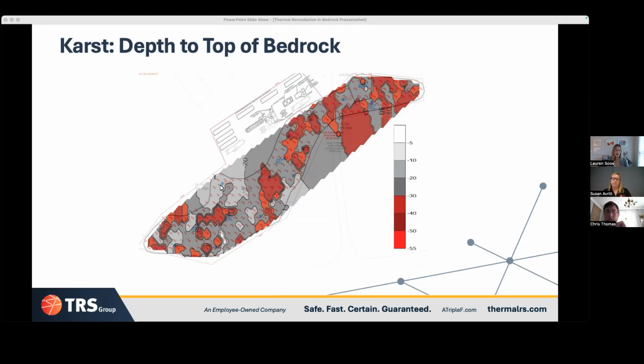And we are monitoring throughout the entire depth interval of the treatment. At this particular site, I believe we use, Chris, was it every 5 feet or 3 feet? Usually our sites are between 3 and 5 foot intervals, but there's temperature monitoring that occurs throughout the entire treatment depth that ensures we are heating up the bulk matrix, not just the fractured zone. Thanks for the reminder.